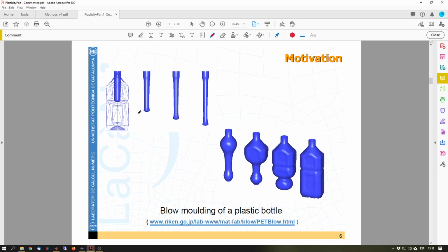Like in this case, you have a mold, like a cast, and then you blow into this material with some temperature control, so you can keep blowing and change the shape, taking advantage of this plastification. Plastification means that if I apply some pressure and see what my length would be, I would keep increasing it, maybe linearly at first, but soon non-linearly, and if I remove my pressure, it would not go back to the initial length that I have here.